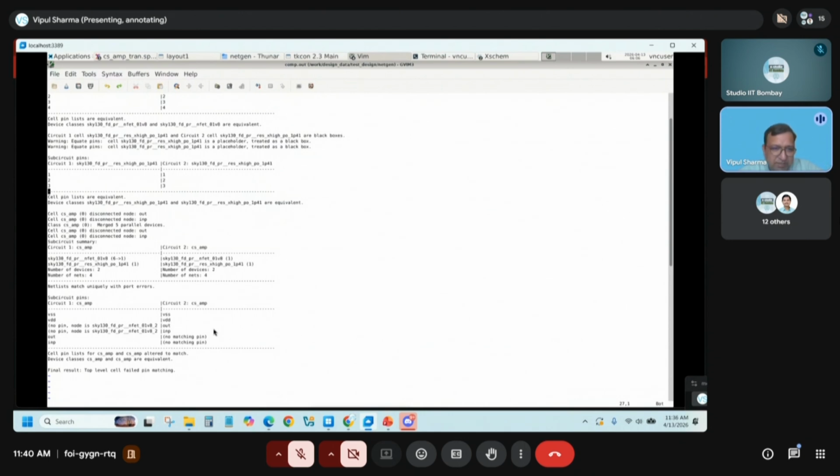If one connection is lost, it might show an error with respect to that connection in another place also. But in this case, we know this was because the net was disconnected. That's why this error is coming. If we correct it again and re-extract, this result will get restored.